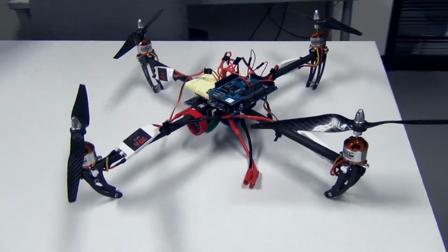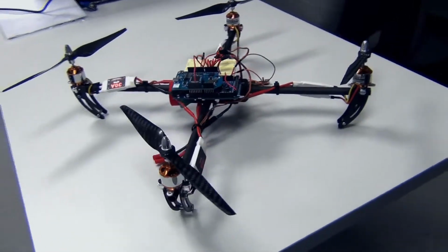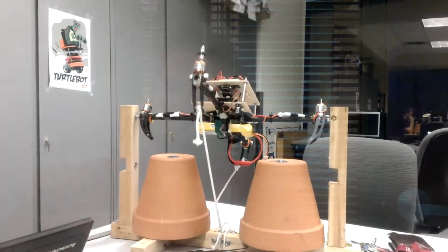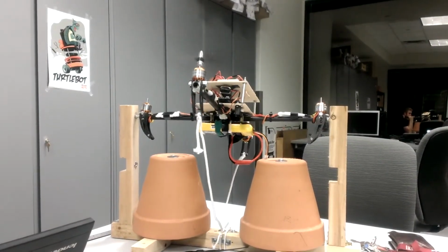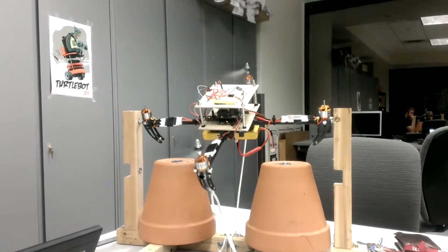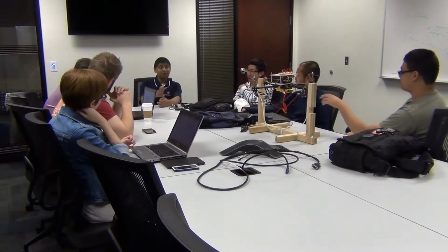At first, we started with a 1-tier architecture with just one board used for pulling all of the sensor data, and then we would do all these computations to get the actual motor speeds that we would need, and then it would send it out directly to the motors themselves, and then the motors would spin at their correct speed. We noticed when we set up the quadcopter that it tended to overcompensate. We set it up on an axis tester so we could just test one axis, and every single time it would dip down, it would just fly back up and overcompensate, and it would just go back and forth and back and forth.